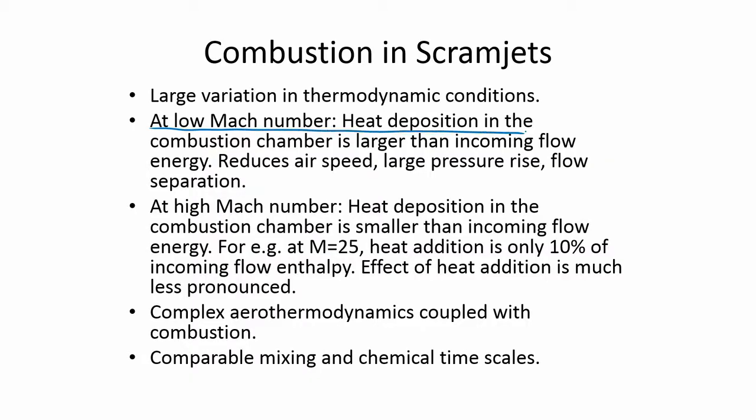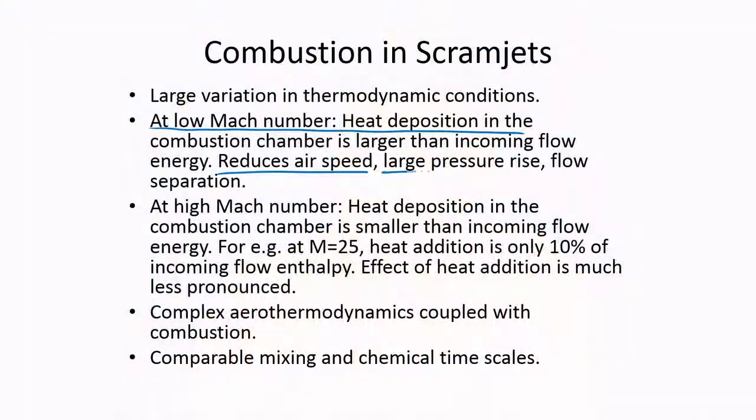Now at a low Mach number, the heat deposition in the combustion chamber is larger than the incoming flow energy. As a result, the pressure rise is also higher, and there are more chances of upstream shock formation. The flow speed is reduced because the heat release effect is very strong, which can lead to a very large pressure rise and also to flow separation.